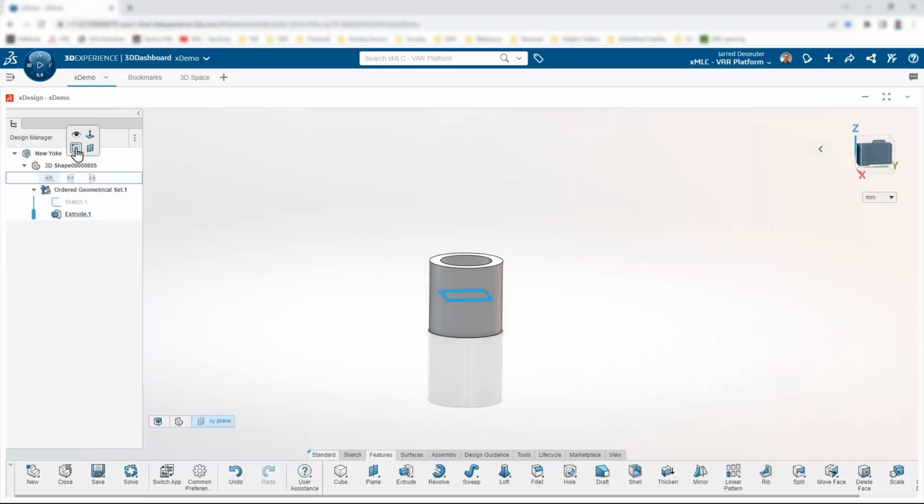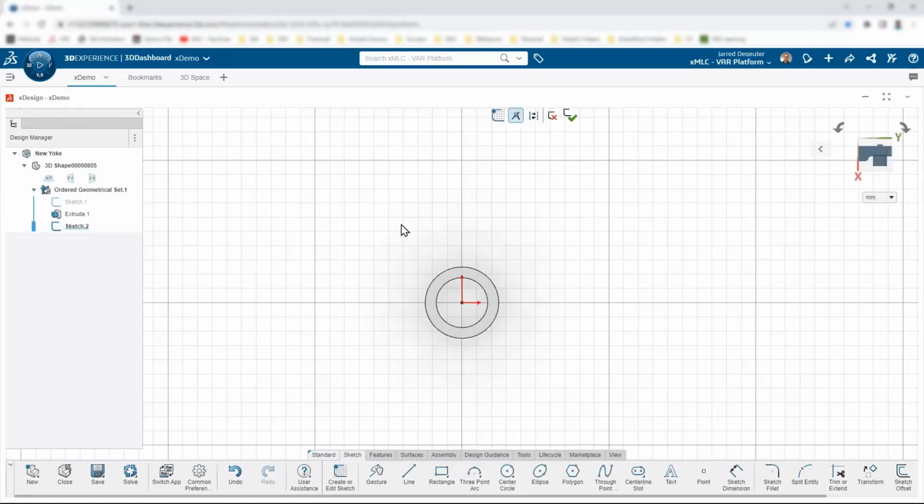Now what I'm going to do is draw up the side portions, the little parts that are going to connect to the monitor stands. To do that, I'll start off with just drawing a little line here. You can see how whenever we're drawing it, it brings up the dimension. That allows us to just key in a dimension and it'll populate it right off the bat. The other thing we can do is click on a line or a sketch entity for that matter, and the dimension will automatically pop up for us. It's grayed out, meaning it's not an official dimension until we click on it. Then we can enter whatever value we need.